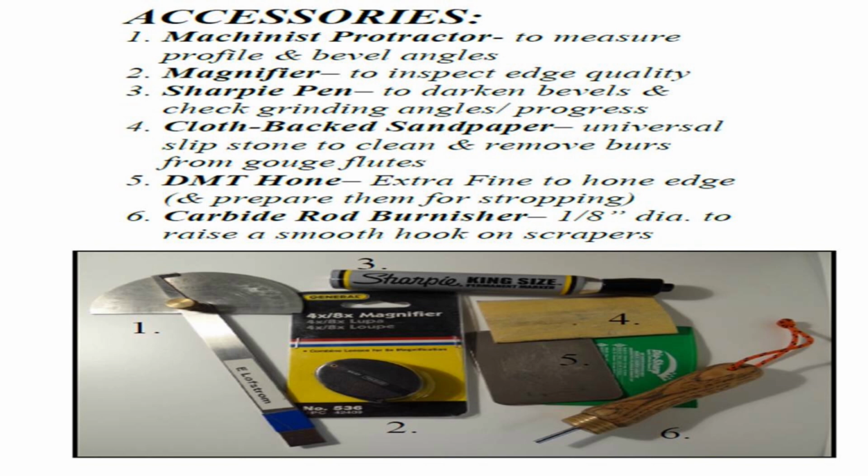The diamond hones, again, we talked about, particularly with the skew, a diamond hone is nice to keep the tool sharp in between going back and forth to the grinders. One of the other areas is on your gouges. As you sharpen it, you'll end up with a burr on the fluted side of the gouge. You can hone that burr, and keep it nice and sharp.